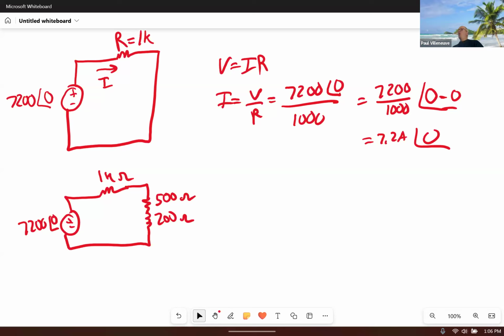So as soon as you open up that device in an inductor, you actually can get an arc. You can generate crazy high voltages. You could damage equipment. A lot of electricians have been electrocuted in the field because they've open circuited inductors, essentially. So that's the other reason why you don't want to use an inductor to store energy, because you can do some real damage without even realizing it.